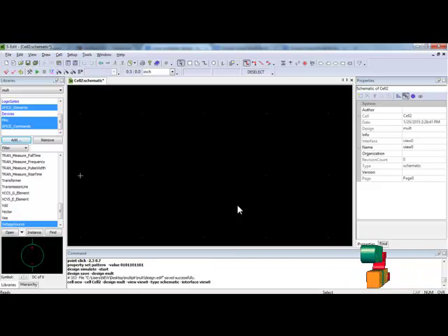After designing this cell, you can save the design, and while you are pressing run, it will lead to T-Spice. Through T-Spice you can see the netlist available. In T-Spice, the components which you have used are listed as component code. That means you can see it program-wise. That's why the T-Spice code is called a netlist. You can run either from SEdit or from T-Spice. From wherever you are running, the output timing diagrams will show in WEdit.